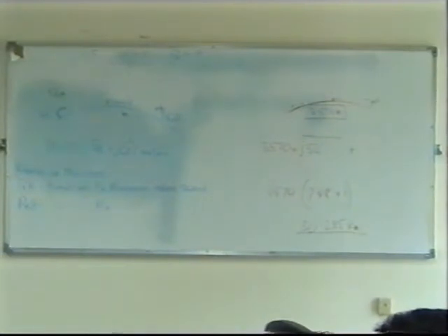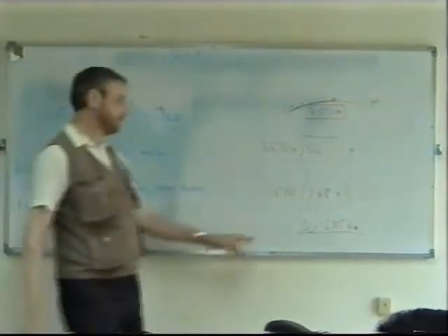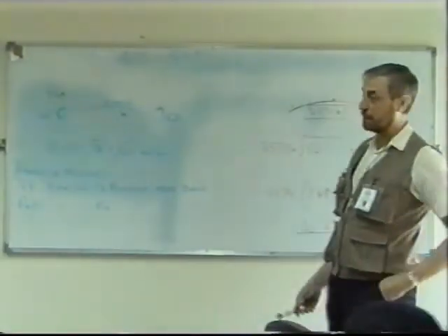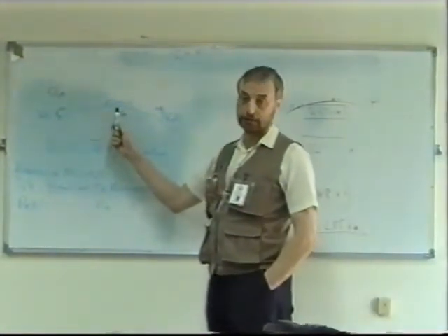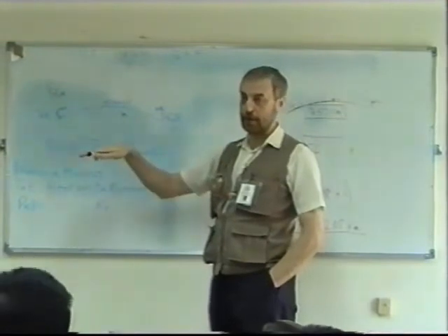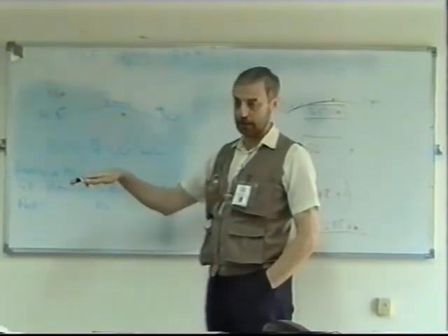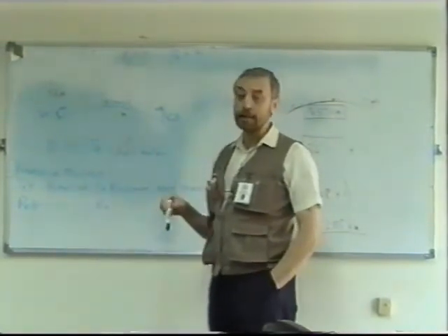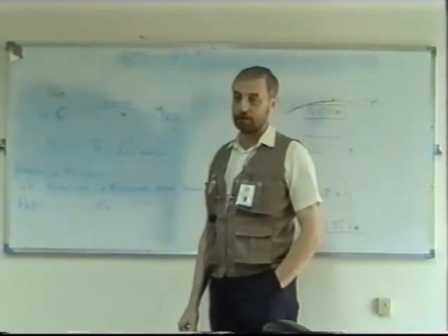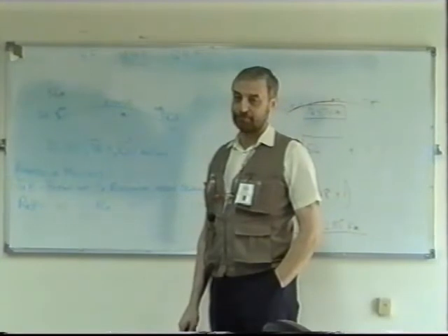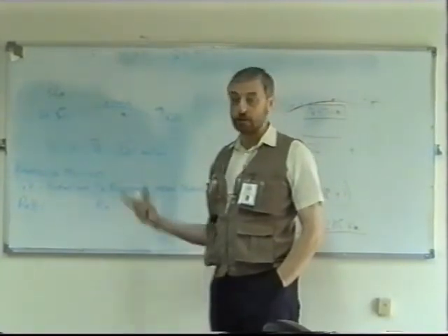What we're saying is that the maximum distance, this 30 kilometers we calculated here, is the maximum range between our antenna and a car, for example, with just 1 meter height above the ground. Now that car can be anything up to a maximum of 30 kilometers. Anything more than that, we might lose it.